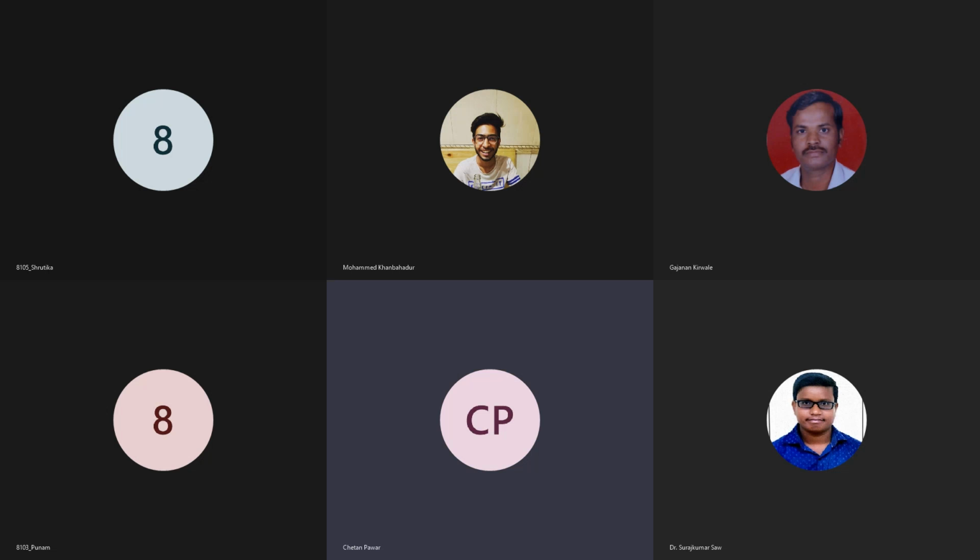Provide the period. No, don't apply. Again, you have to fill all this. Provide the period, whatever you want. 100 nano. Okay. Delay time. Don't give so much delay because you have a 100 nano pulse, and it will start after 50 nanoseconds. Let's give 10 nano. Okay.